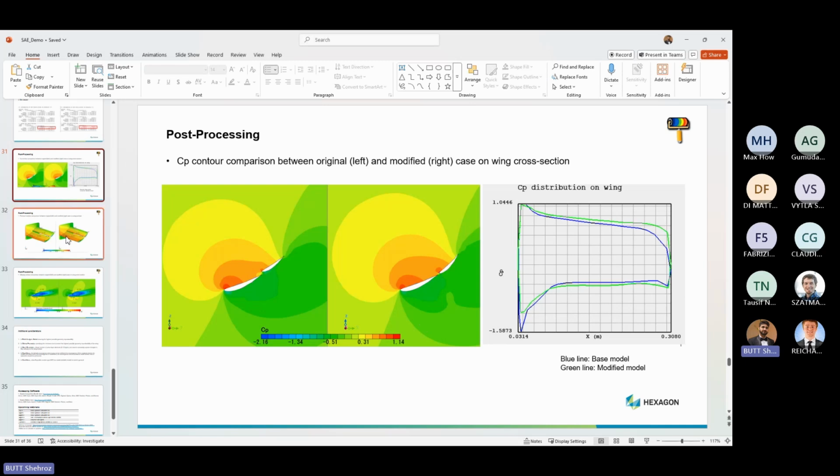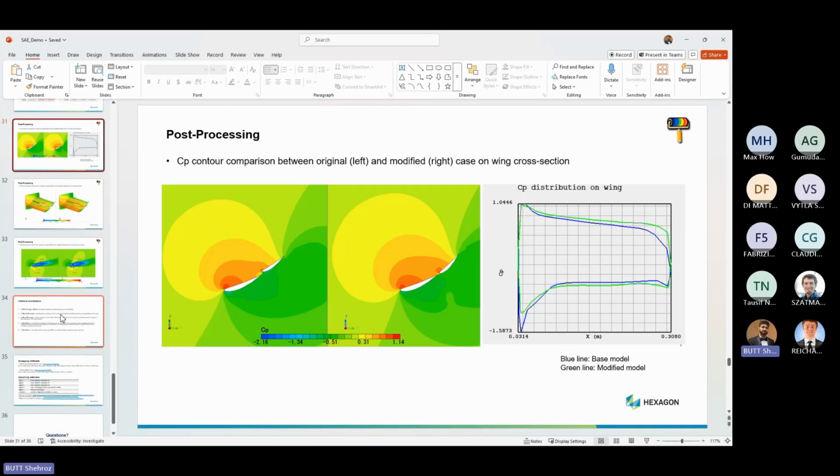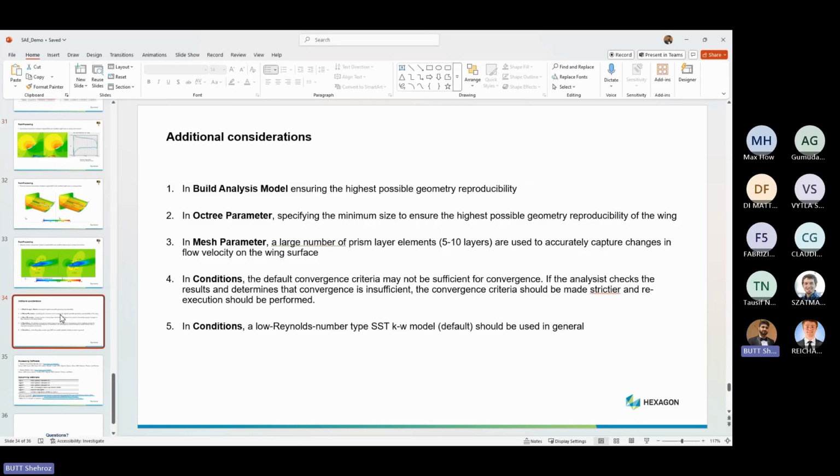and you can do various simulations. As I mentioned earlier, the quickest way, rather than changing the geometry itself, will be to change the inflow direction to reflect the angle of attack. Now, just a few considerations before you jump into the conclusion of your results.